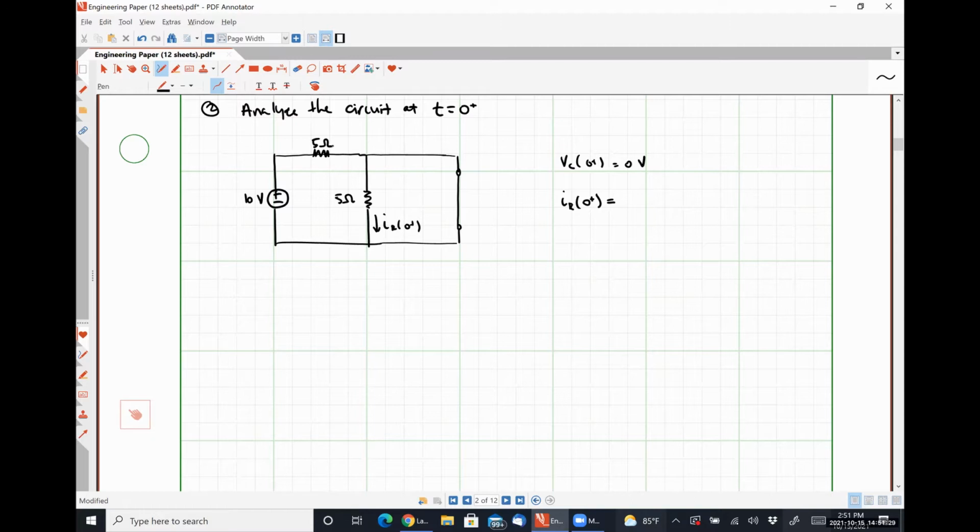Because they're all in parallel, I was forcing the voltage drop across my short circuit to be 10 volts, and it can't be that. That's exactly why it's an ideal voltage source. So it can't be connected to 0 resistance because that is forcing a voltage and no voltage to occur simultaneously. Can't happen. Two can't be 1, right?